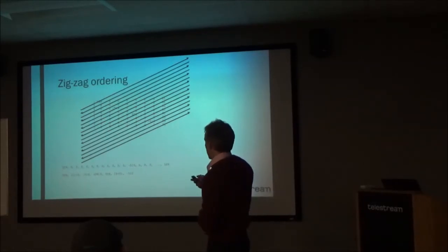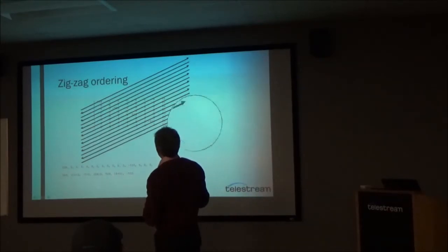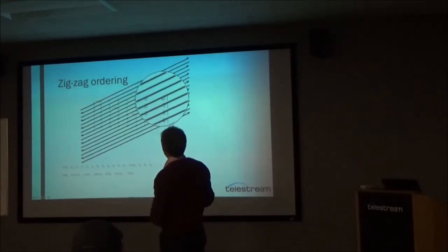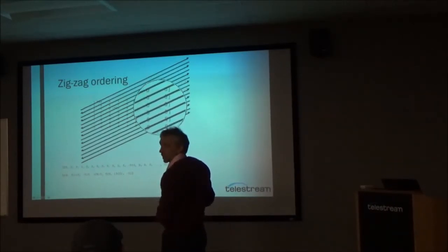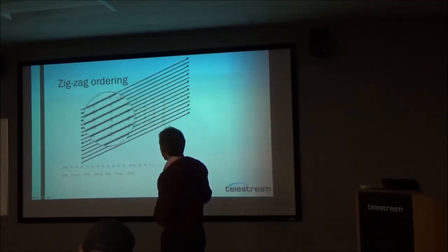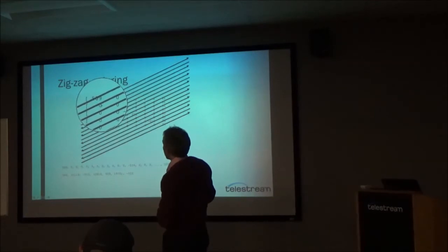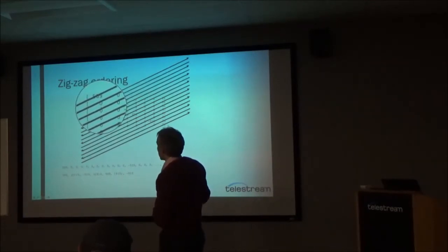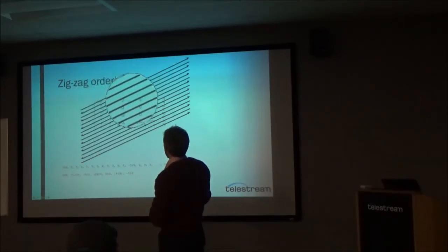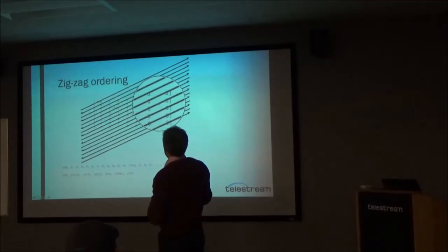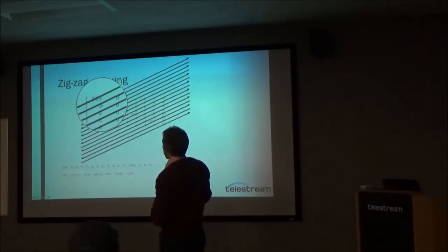And it turns out that it's very likely to say that this one over on the right-hand side is a 0, because it's one of those high-frequency things that we're going to quantize quite a lot. But it's quite likely that this one is not going to be a 0, because it's a very low-frequency thing that we're not quantizing very much. So if I just ran the ordering from here across, I would probably go here, and this would be a 0, but then I'd jump back over here, and then this would be not a 0 again.